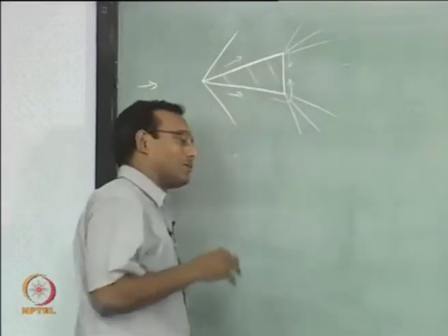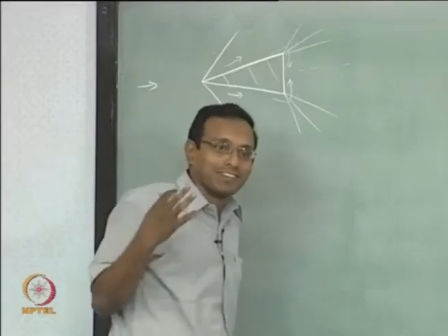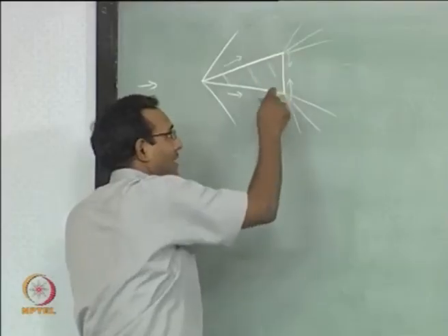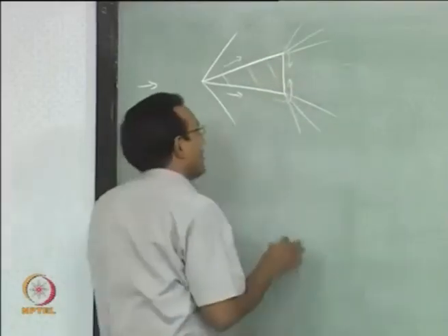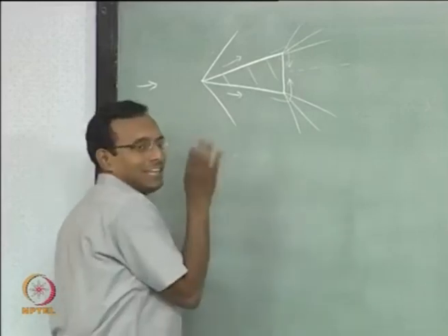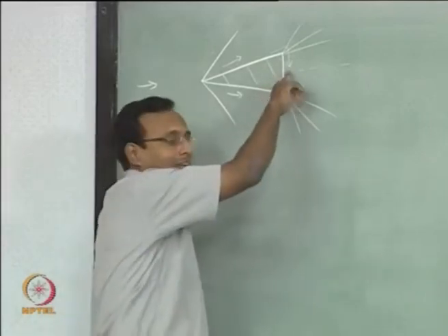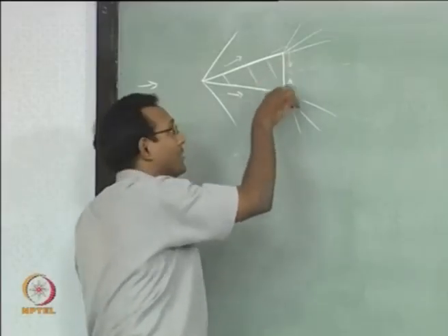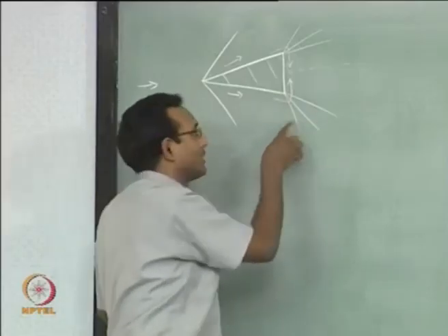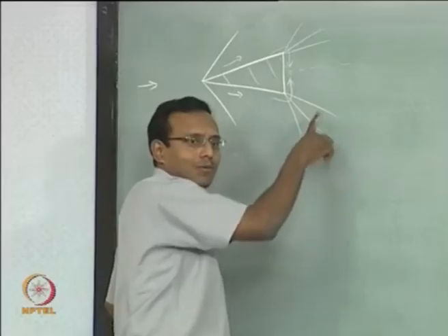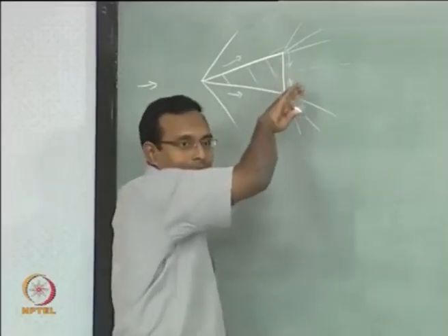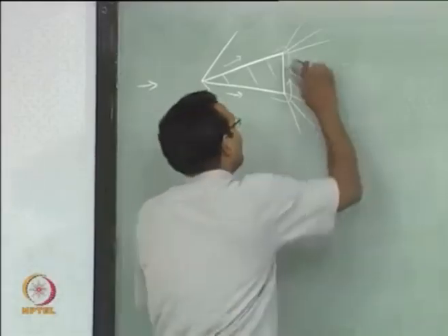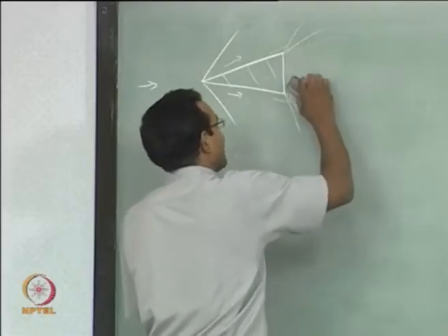Okay. We will probably go to this problem if I get permission to use some book on video directly, but as of now I am going to say that the flow will come hit head on and then figure out what to do. Okay. What really happens there is, initially they will come and hit, and then they realize that there is no space, so there will be extra shock wave coming here which will come and neutralize this expansion wave, and so the expansion wave decreases in strength. What does that mean? It cannot turn as much. If it does not turn as much, all this I am talking about is all unsteady world. Okay. All this is happening for the very first time when the flow starts over this body.